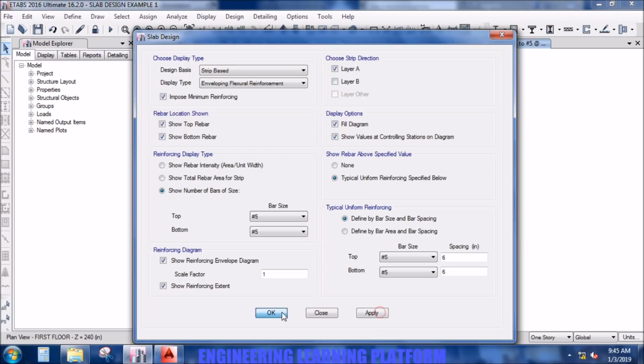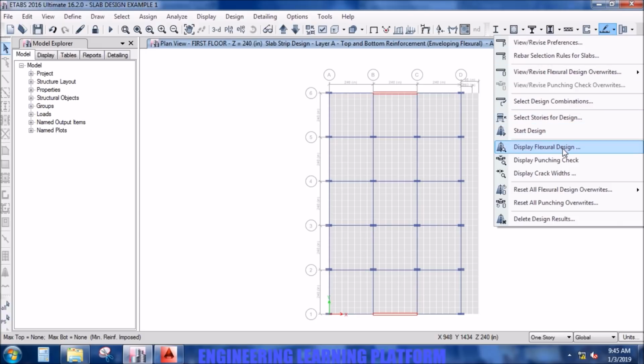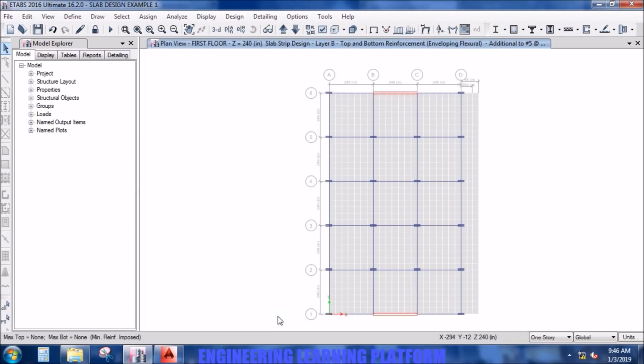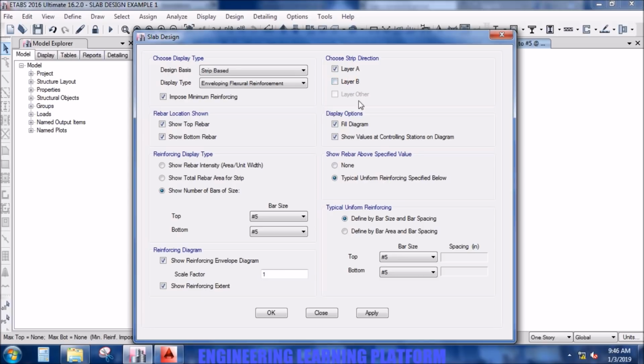Define the bar spacing for uniform mesh which you want in the slab. Since the spacing we selected was high, so now for less conservative design or more economical design, you may increase the spacing so that you may get extra bars here. So the mesh is also over designed here, so we may increase the bars or decrease the bars, or increase the spacing, or you can say increase the spacing by decreasing the bar density. Sometimes the spacing option freezes.